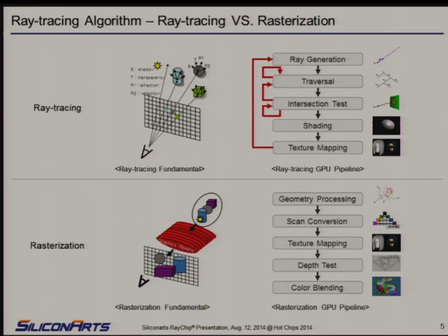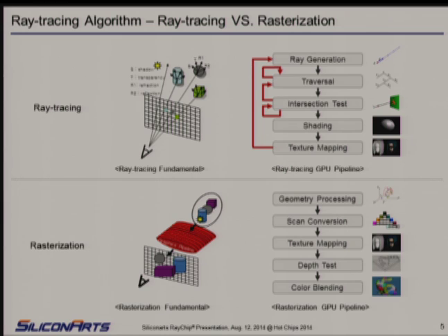Now, the rasterization pipeline maintains a simple stream process by projecting each triangle to the 2D screen. Whereas for ray tracing, this pipeline contains recursive loops, which are the key to its ability to compute global information in the scene, but it requires a huge amount of hardware resources for computations, and it is even harder to implement into small silicon of real-time applications.